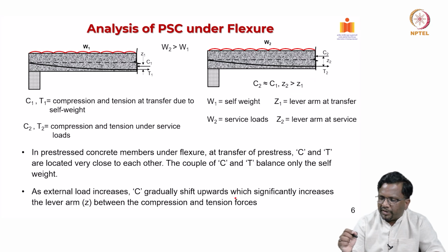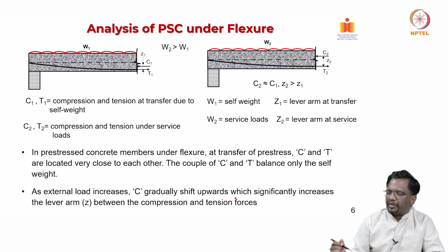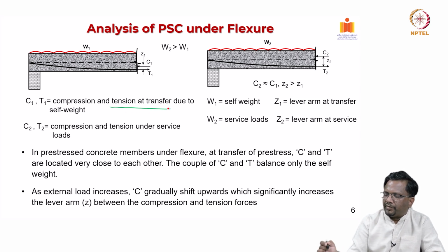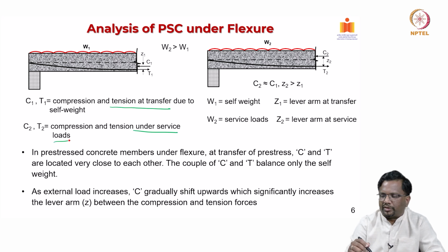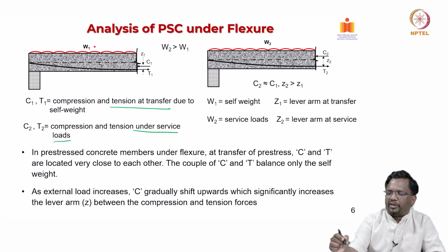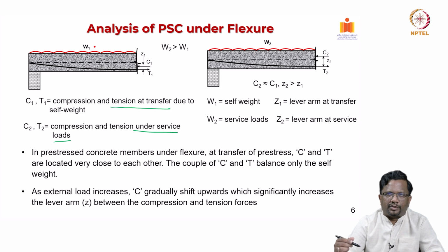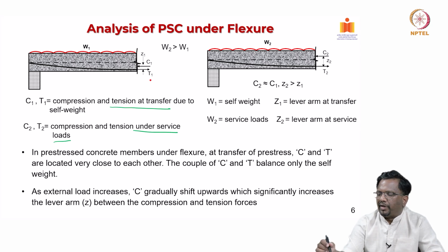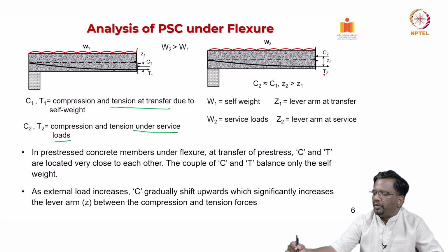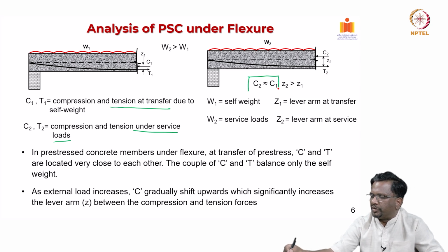But if you go to a pre-stress concrete member, we have seen again two cases. You see here, we are looking at a transfer due to self-weight, and this is under service load, C2 and T2. So, two conditions, W1 is at, let us say, transfer, W2 is at service load. Now, if you look at the internal forces C1 and T1, and C2 and T2, we will find that the internal forces will be nearly the same.